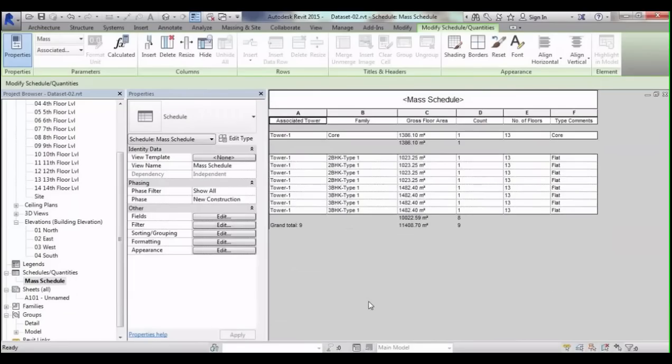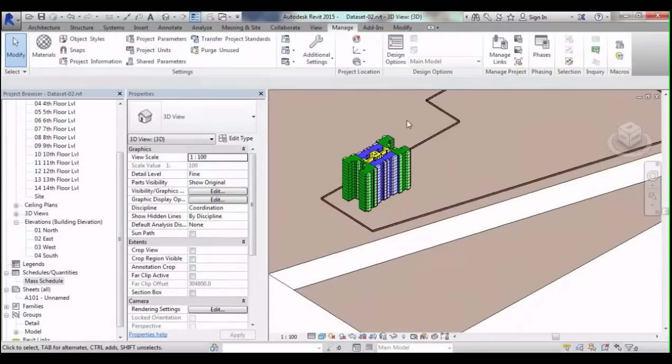Now I would like to mention one more thing before moving forward. The masses which I have made, I have done as a mock. I've done my planning, say I've designed a 2 BHK unit or a 3 BHK unit and a core, and an 8 to a core arrangement, and then made my mass models. You can even do it the other way around. You can decide on a footprint of your building units in a mass and work out with the schedules in the best possible way to get the efficiency, and then check whether you are able to design within that space or not.